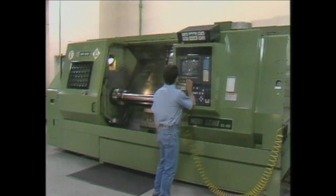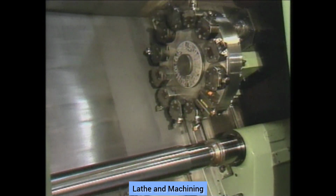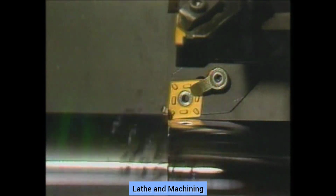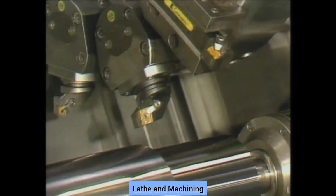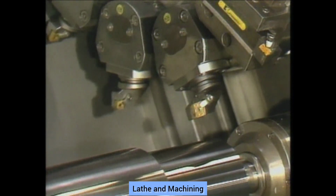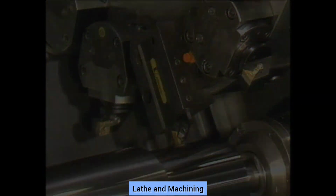The two-axis single turret CNC lathe is the simplest CNC turning machine. All tools are in a single turret, which is on a slide moving in two directions. Hence, it is designated a two-axis lathe. One cutting operation is performed at a time.